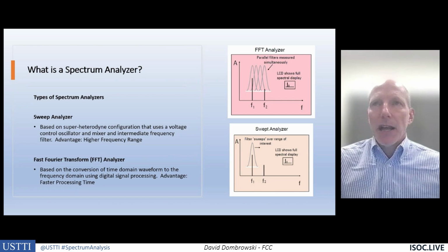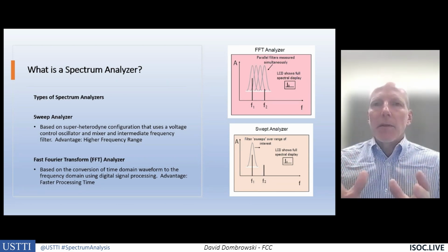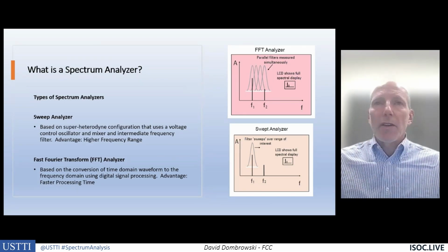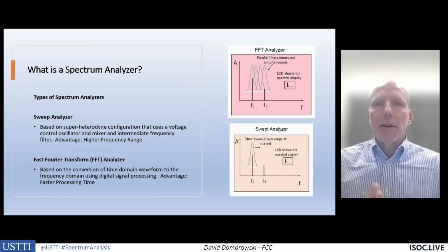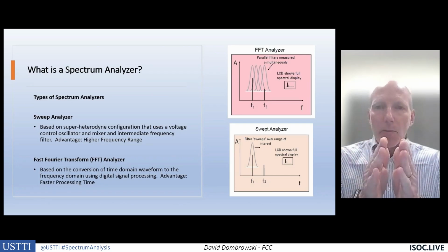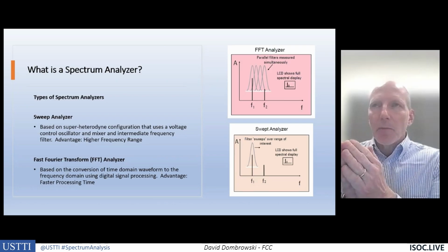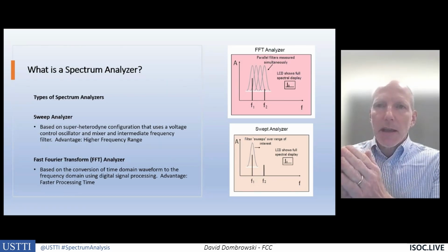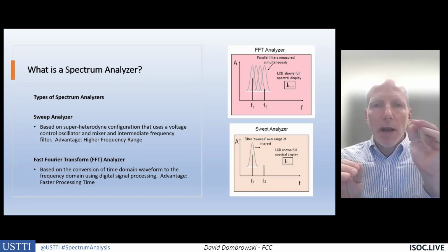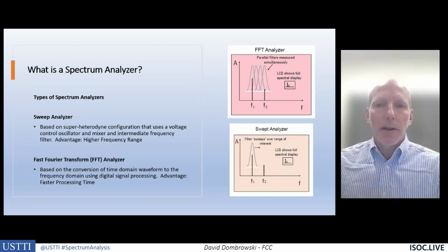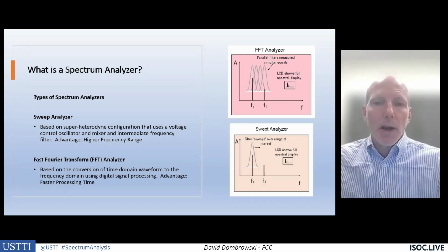And we can differentiate them. If the beam width of the satellite dish is narrow enough, which they are, with dishes that are 20 or 30 feet in diameter, we can point that antenna right at the satellite of interest and pick out the signals just from that satellite. We're not picking up the signals from the other satellites because of that narrow beam width. Hopefully that answers your question.